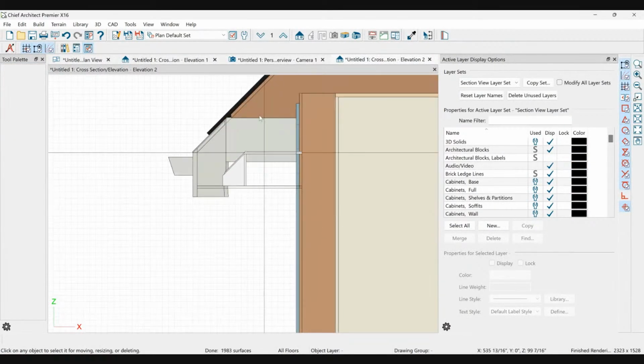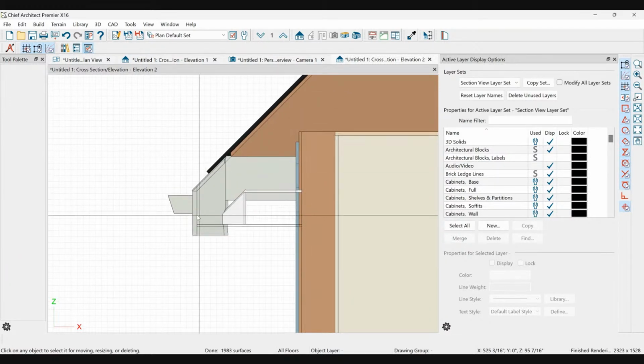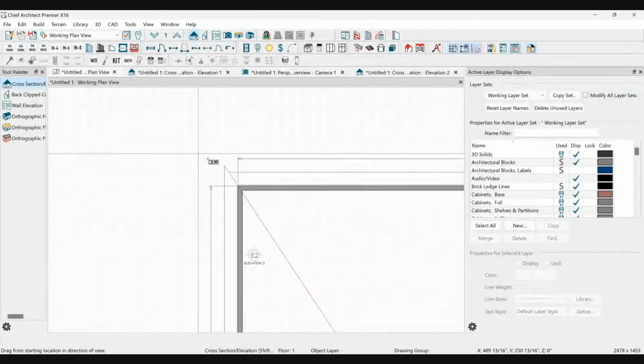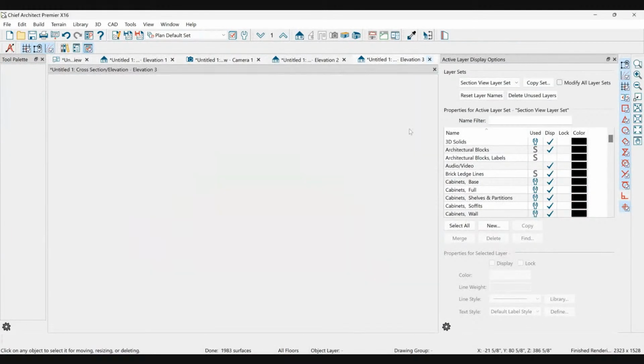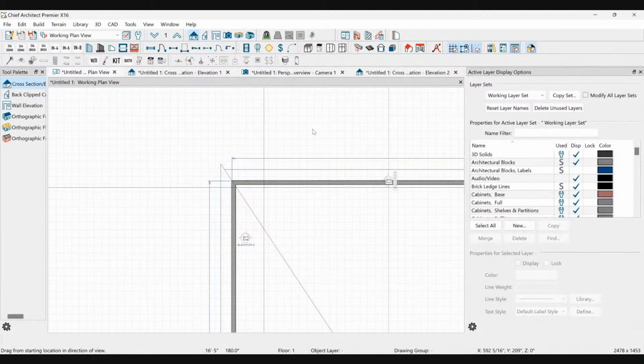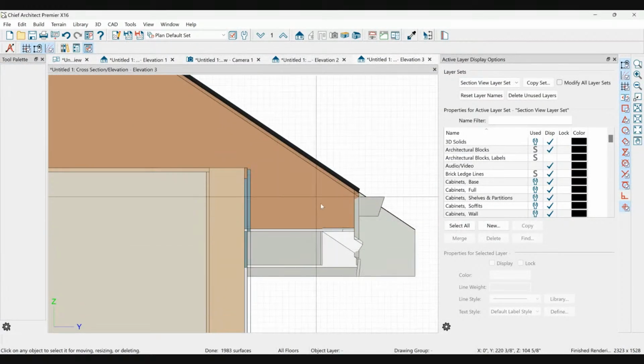Okay, so this is your soffit as the roof is steep, right? So if I go out 16 inches and I have a steep roof, my soffit's going to drop down much lower than if I cut this way. Oops, that's at an angle. That's going to be confusing. If I cut the wall that's shallower, right, my soffit is going to be less steep.